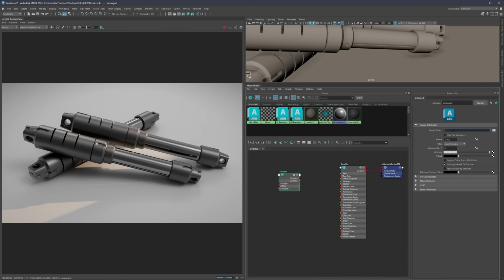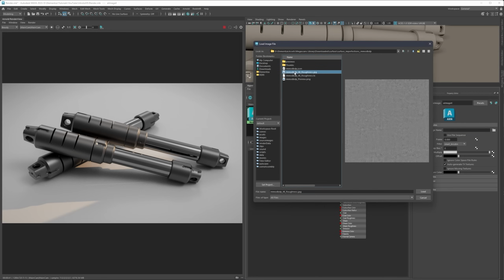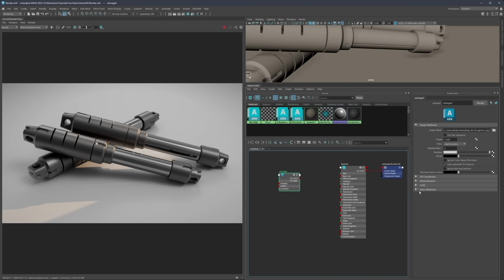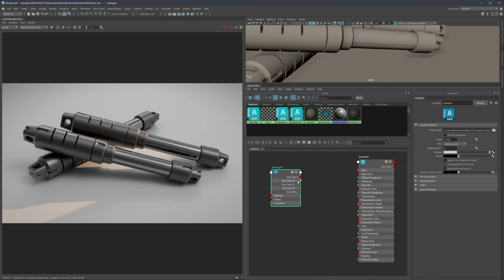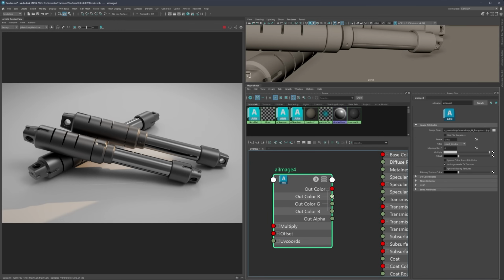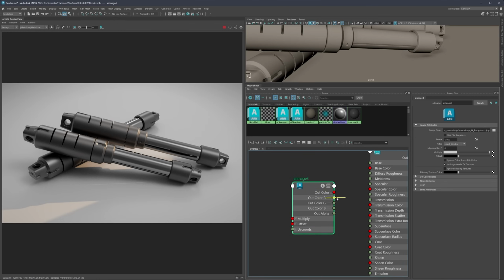So the thing is, when we load any kind of image, let me load an image from here. So here I have from Megascans some roughness images, and I'm going to load this one and simply hit load. All right, and now when we have an image, we need to connect the image to our roughness. And basically when you see a red connection, a green connection will not really go. It's going to be either green to green or red to red. But if you expand the red here, you're going to see that we still have some green nodes here. So you can also connect those.